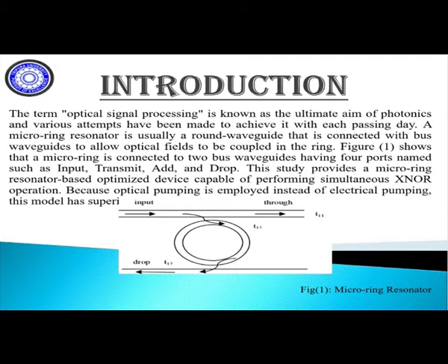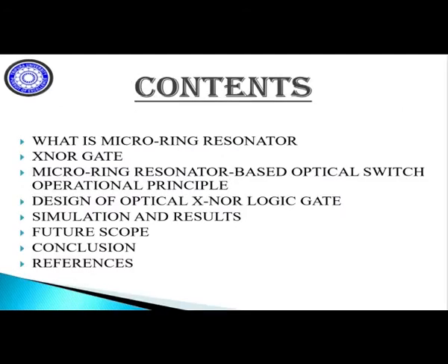The study provides a microring resonator based optimized design capable of performing simultaneous XNOR operations. Because optical pumping is employed instead of electrical pumping, this model has superior responsiveness. Next, I am going to explain the topics: what is a microring resonator, XNOR gate, microring resonator based optical switch operational principle, design of optical XNOR logic gate, simulation and results, future scope and conclusions.